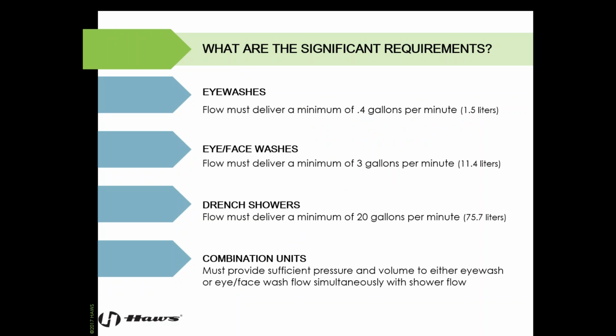So we're going to go through the different types of equipment that are specified in the standard, and those are eye washes, eye face washes, and drench showers. Oftentimes, eye washes and eye face washes, those terms tend to be used interchangeably, but they are absolutely different and they provide different coverage. So for some of you it may be intuitive, others it may not if you haven't worked with equipment like this. So an eye wash essentially covers and flushes the eyes. An eye face wash has more coverage, will cover the eyes as well as the face.